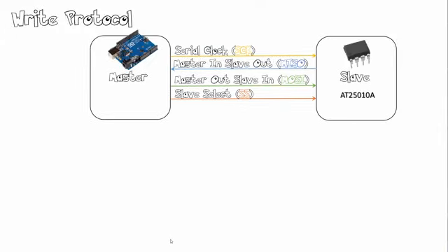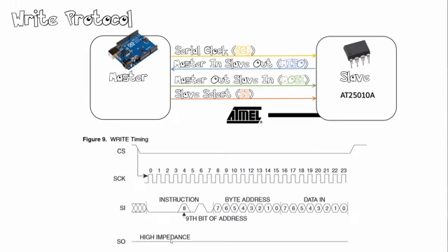Let's take a look at the read-write protocols, or data transmission protocols. If you've got a single slave configuration, we can look at, say, an Arduino, which is talking to a slave, which is an EEPROM device. Atmel has a device called the AT25010, and by using SPI, you can really communicate fast with this device compared to I2C. As I mentioned before, with SPI, every company has their own transmission protocols, and you have to read the datasheets on how to communicate with each peripheral.